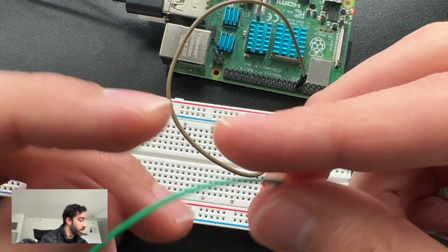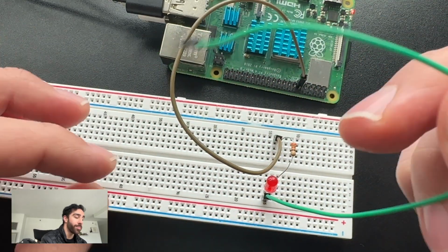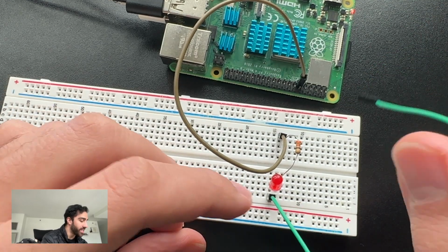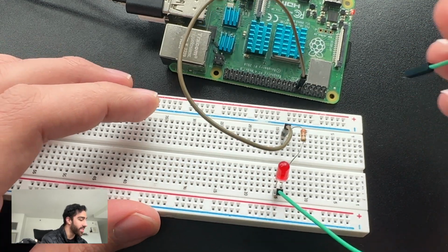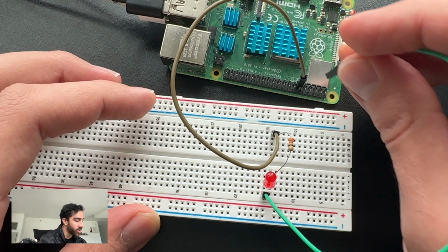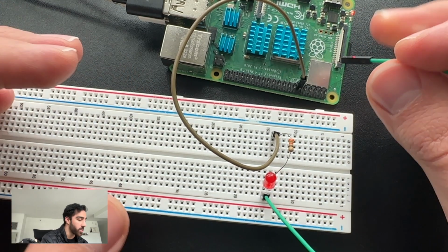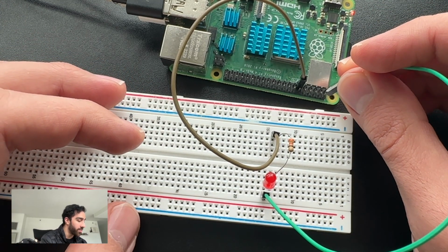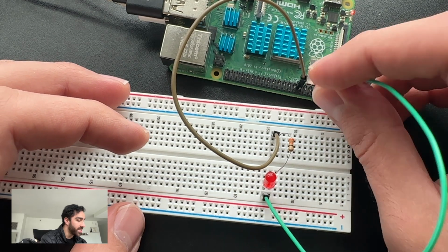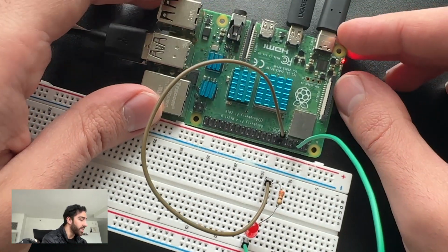This is just going to complete the circuit. Remember how we talked about the ground pin is for completing the circuit? Well, this is the ground pin. It's connected to the shorter end of the LED on row 15, and we're just going to connect it to any ground pin on the Raspberry Pi. I'm just going to use this 3rd pin from the top. So 1, 2, 3, and that is this 3rd ground pin. So this is the completed circuit.